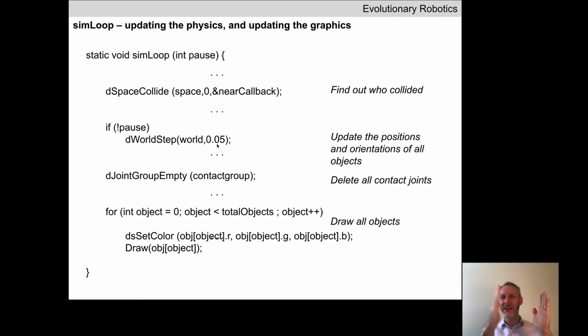So we're simulating 10,000 seconds inside the simulator. We could reduce the time step to 0.05, which reduces it by 20 times. So we would do 20 times 10,000 time steps. We could simulate the same period of time if we set num time steps to 10,000 times 20 and used a smaller time step.